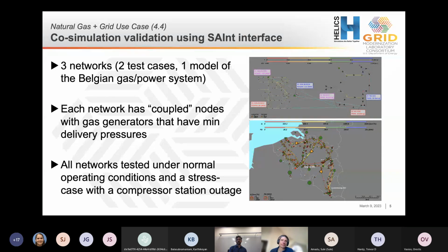Hey, Brian. So what level time step did you have to implement to make sure that the response was realistic? Yeah, so the gas networks that we've run with, the way that I think users often run them is like a 15-minute time step, where they solve it every 15 minutes, but they're also adjusting or ramping up through that 15 minutes.